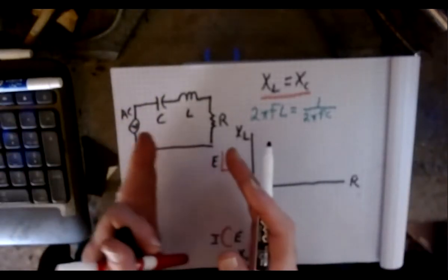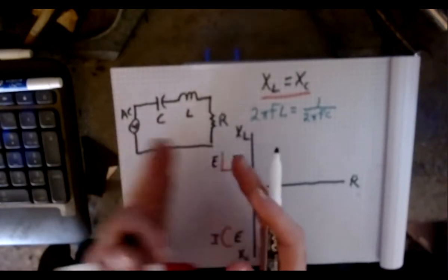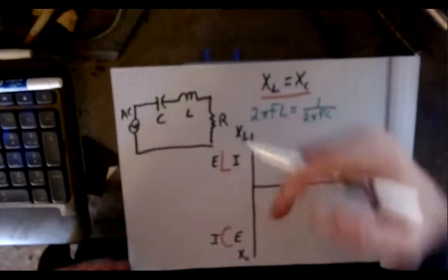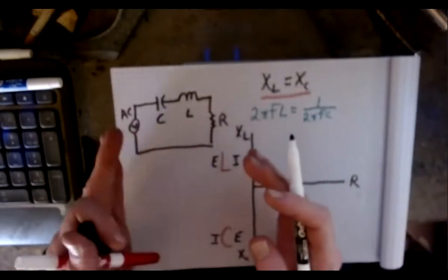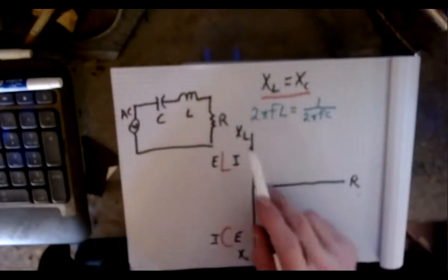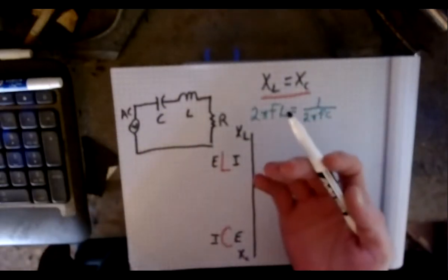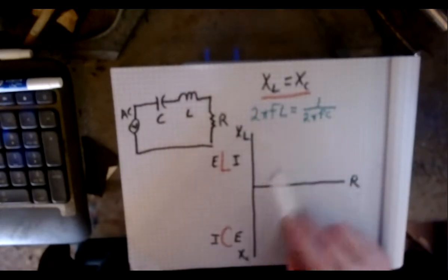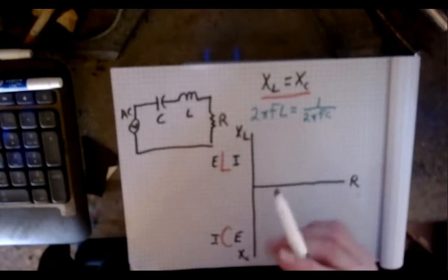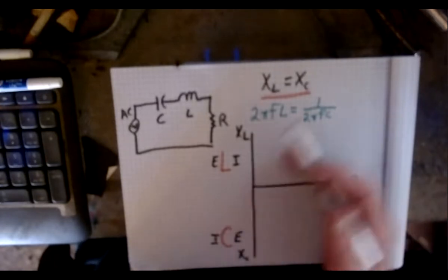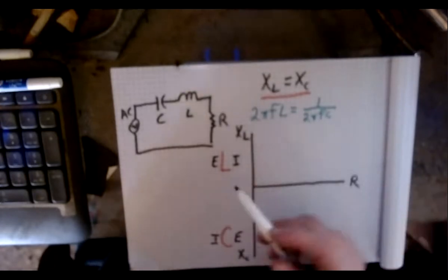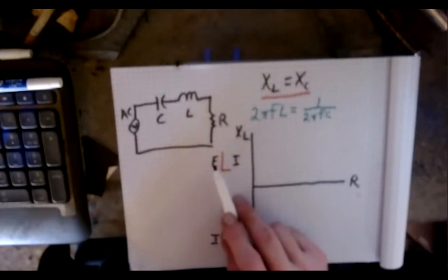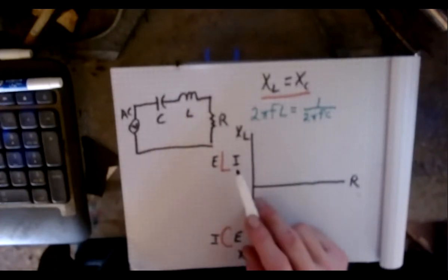So the voltage starts to pull ahead of the current as we swing more inductive. How much more? That would be the ratio from the arctangent formula. If we had something like 30 degrees or 50 degrees, that's how much more the voltage will lead the current.